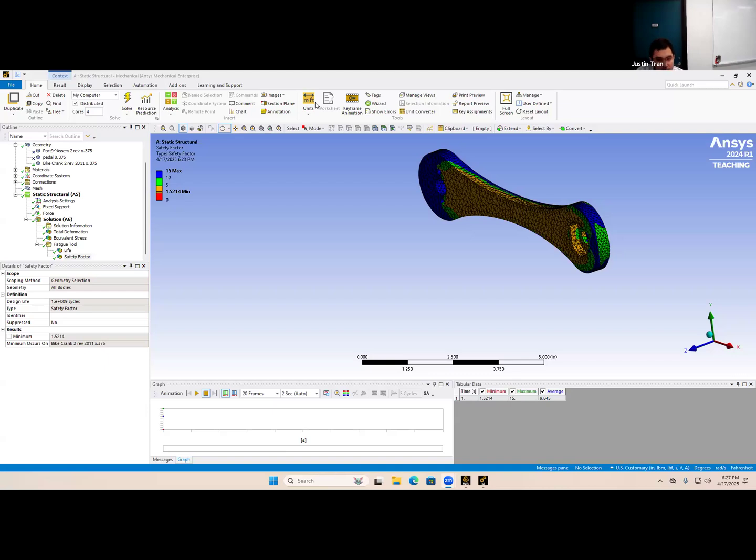So the shell element might struggle there a little bit, but I would try it. See if you can get a mid surface on it. I think it's definitely worth trying. And if you're having trouble with it, then maybe you can look at it. But it is possible to get a shell for a curved surface, for sure.